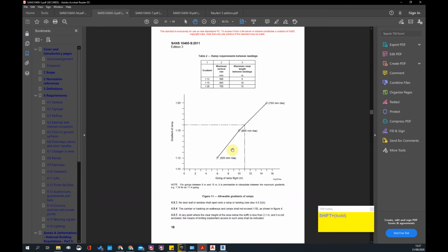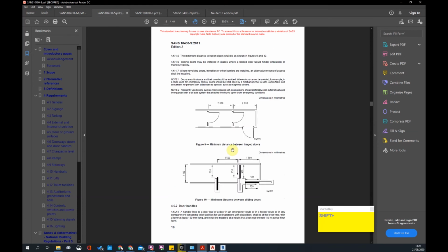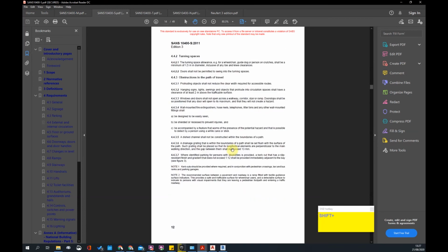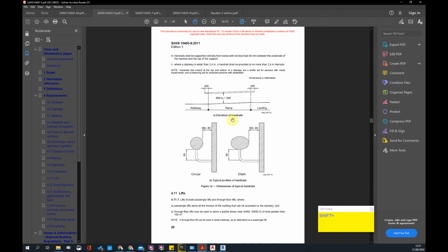But if it's a barrier, 1,000 high. In the UK, it's 1.1. Okay, it should be the same here. I just don't understand why it's not. But anyway, that's why I'm saying you need a 60 mil gap when you're putting your hands, so when you're going up and down the railing, you don't hook your hand on something.